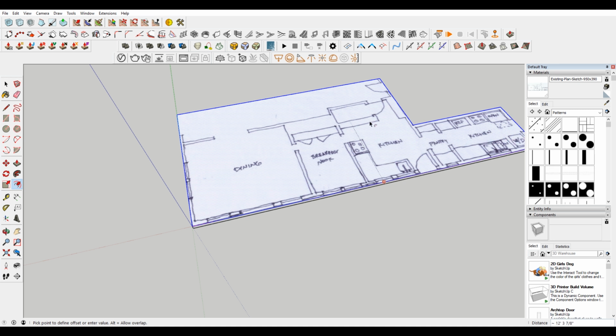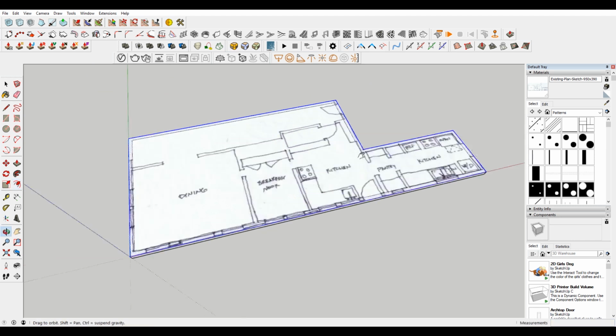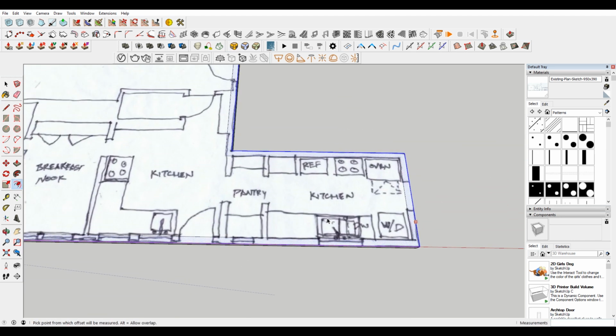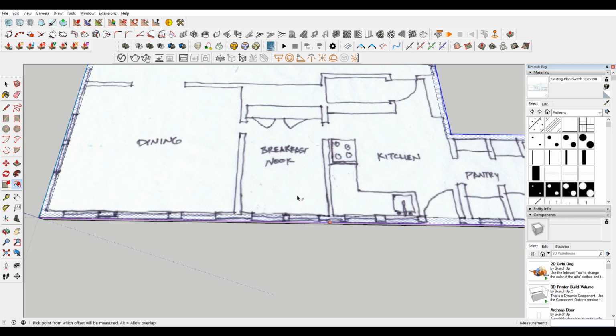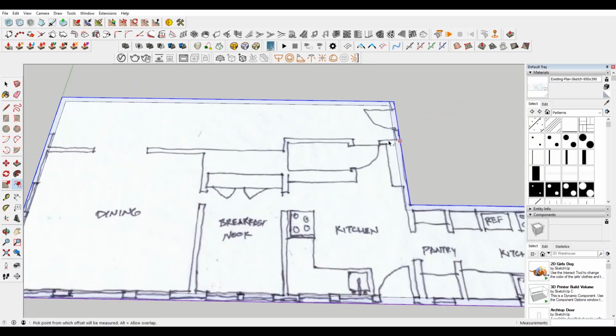It's what I've used before on my drawings, and then typically I use 5 inches for interior walls, unless you need to put extra stuff in them. Like bathroom walls might need to be a little bit bigger. So that looks actually really good, that 7-inch wall all the way around. There's some weird stuff going on here, but that's fine for what we're doing.